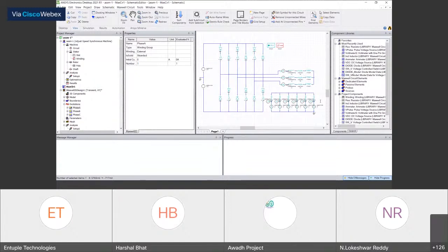Can we predict the breakdown of dielectric material of a transformer by adding impurities? Well, not really. The breakdown of an insulation is itself a chemical change. The Maxwell solver is an electromagnetic solver, so a chemical change is not something Maxwell can calculate. A breakdown will not be done, but it can tell you the electric field stress in the insulation.